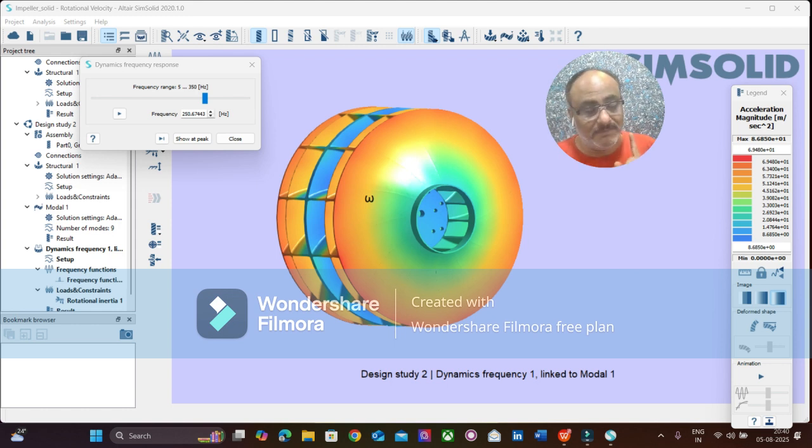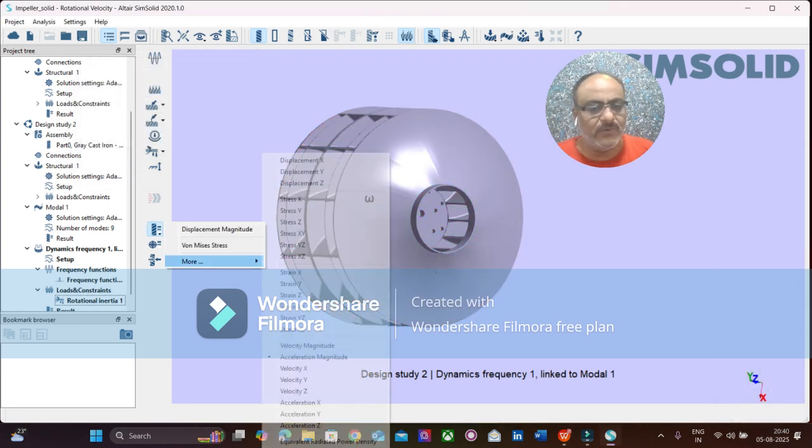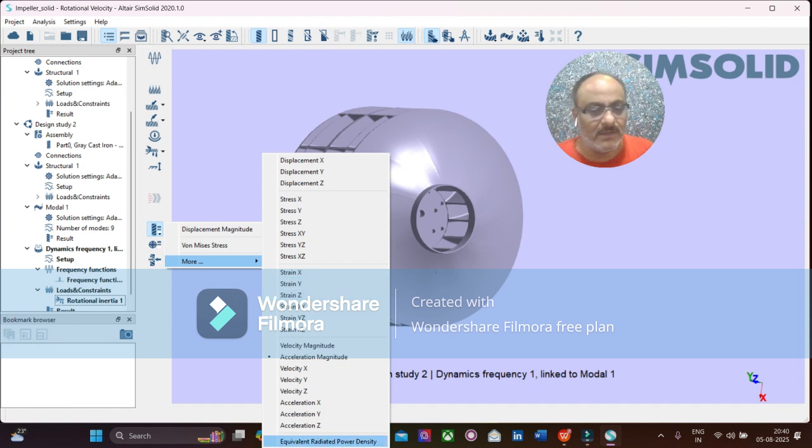Now if the impeller is not able to sustain this 7 G load, then again there should be an optimization or a design change done. We need to do some additional modifications. We need to brace it with some additional stiffeners, or we need to increase the thickness of certain members, the plates here, the top bottom stiffeners, or we need to look for an alternative option about reinforcing the collar. So we need to understand a lot of other things. Now let's study the other one.